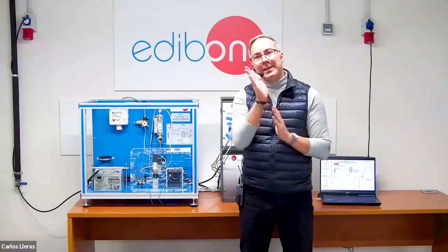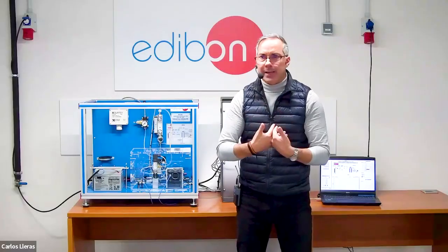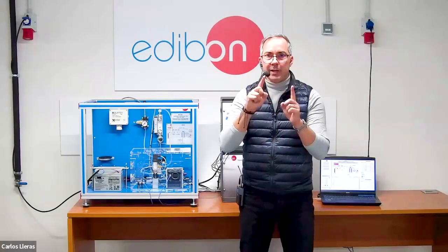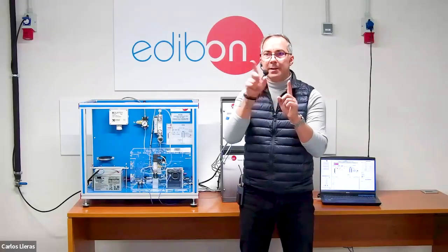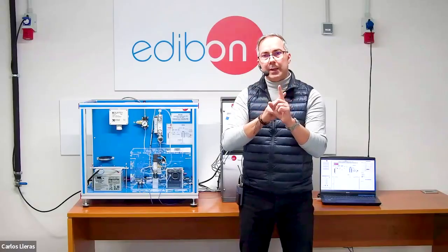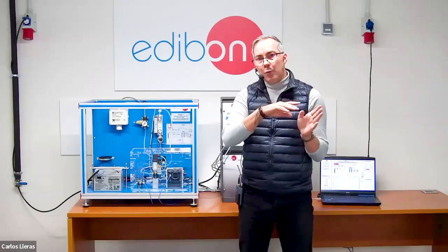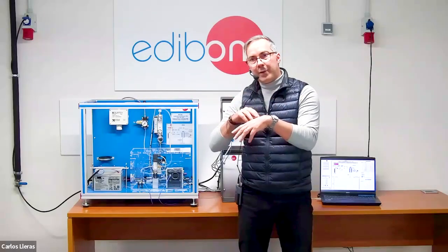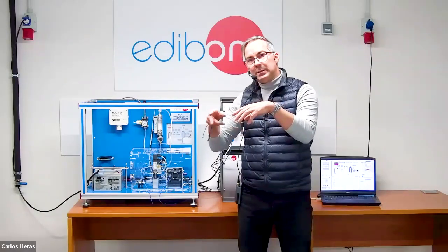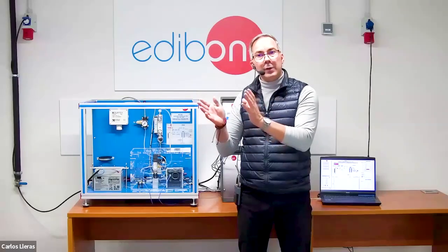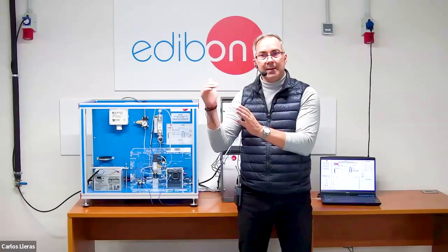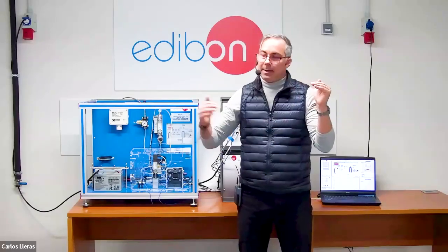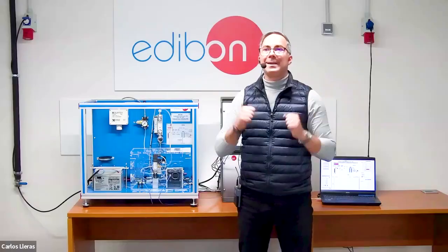Okay? So that displacement of electrons creates energy, creates electricity. If we plant a light bulb in that bridge where the electrons are moving from one side to the other, that will create electricity. Okay? What happens when those electrons go to the other side and meet again with the previous protons that were going through the membrane? Well, they will combine with the oxygen that is coming from the right hand side. So we're filling hydrogen on the anode side, and we're filling with oxygen on the cathode side.